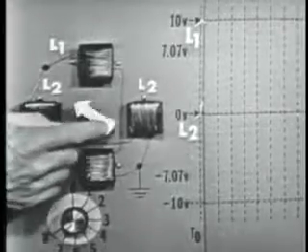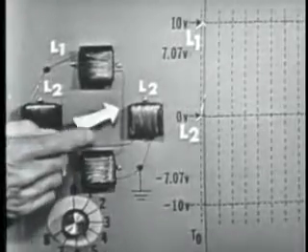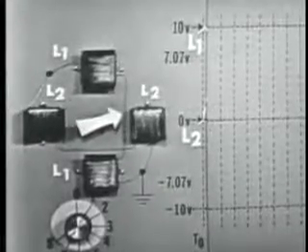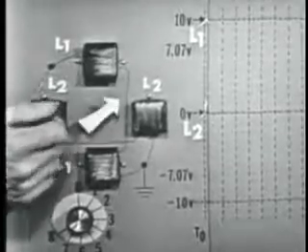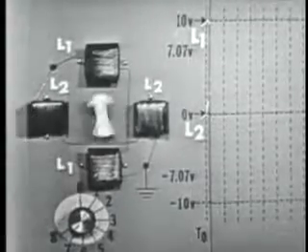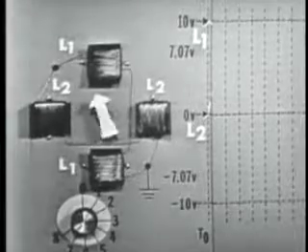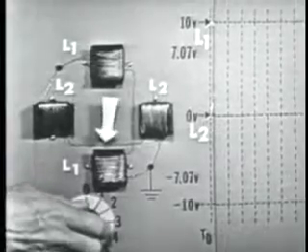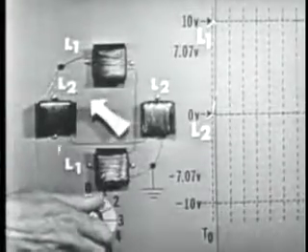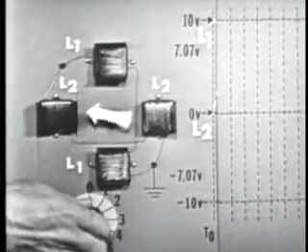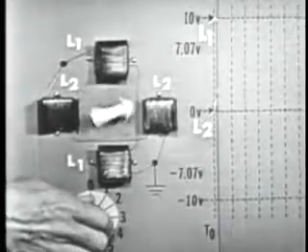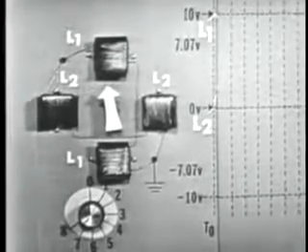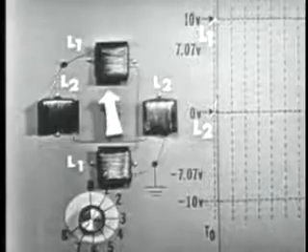Now, in the center of the coils, we've placed a permanent magnet with an arrow on it to show the direction of the magnetic field at any one time. This permanent magnet is simply glued to a ball bearing so that it can rotate freely. Now, the object of this demonstration is to cause this arrow, this magnet, to rotate 360 degrees by causing the magnetic field produced by these coils to rotate 360 degrees. So that you can understand exactly why this happens, let's take a look at the way these coils are wound and how the voltages will be applied.